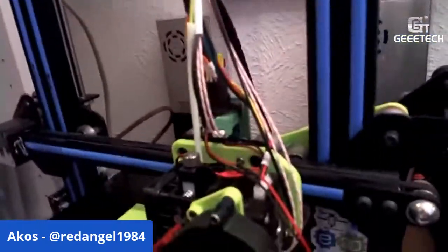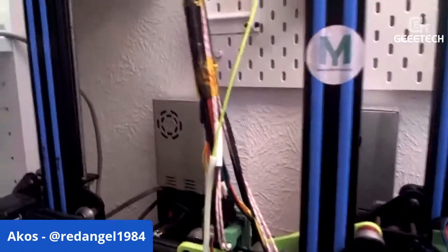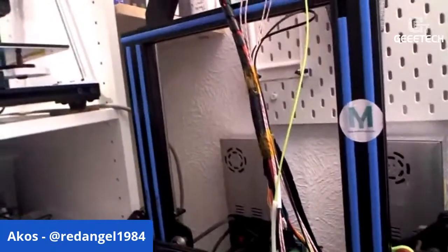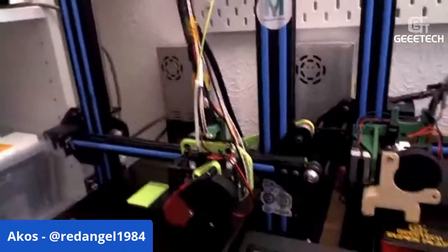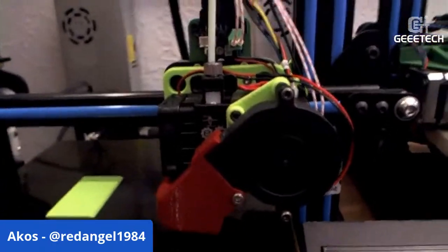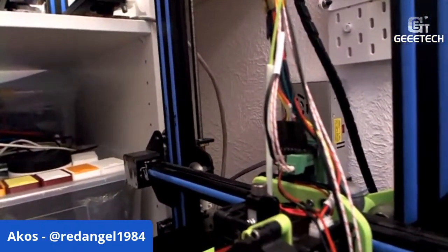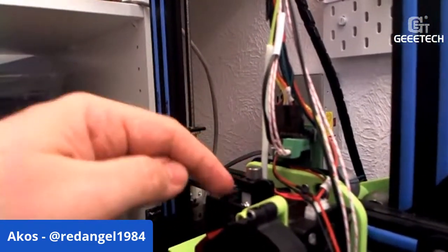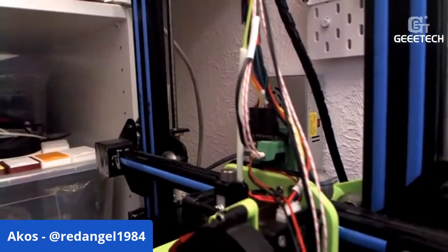The other one is here, the extruder. Everyone knows that the A10M comes with a multiplexer two-color extruder and nozzle, but I found out that I don't really like this combination because I don't print two materials so often. That's why I decided to upgrade the hot end and also the extruder. I chose this direct drive extruder. This is the E3D Hemera. It has a great feature: the extruder has a very short path, so everything is pushed directly from the gear into the nozzle. It's a very reliable little extruder.